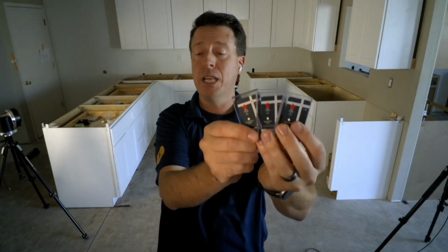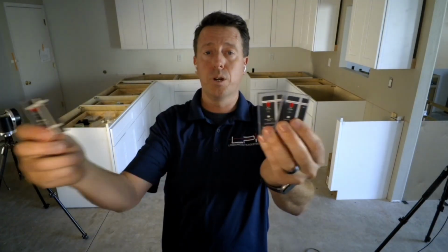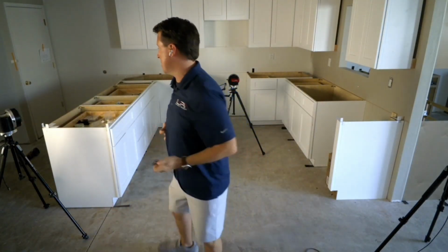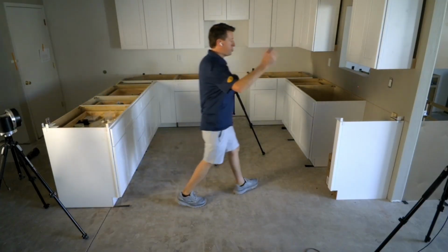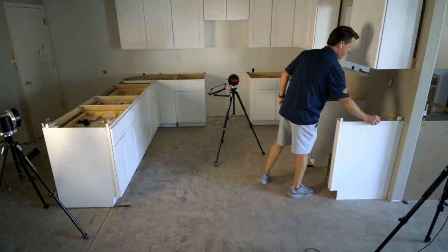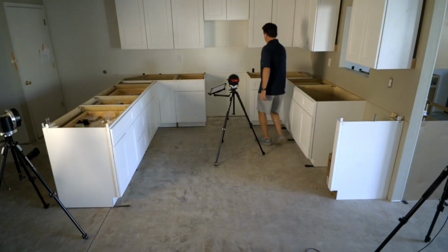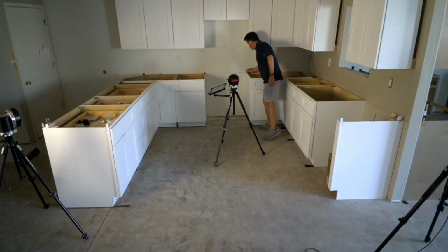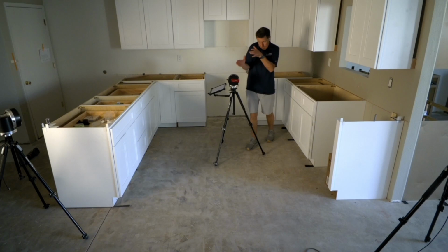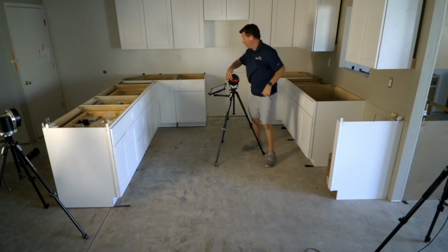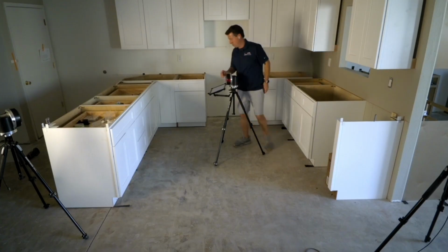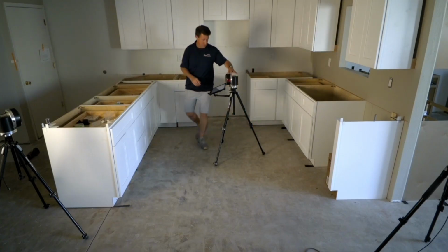When we set that plane using that triangle, we set these out in space, and generally I want it to represent the majority of our measured area. If we set these close, and my laser dot's a little high or a little low, as that plane extends over a large area, we get a less than accurate plane. So the order does matter, right?